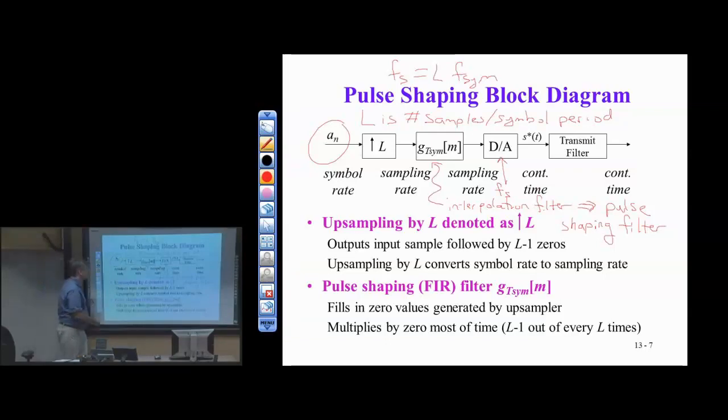Okay, now this is the part of the baseband processing. Then after the D-to-A converter, it will go through some subsequent processing before final transmission. So a modem consists of a baseband subsystem and some analog front end. So this class is focused primarily on the baseband transceiver. We don't do very much on analog integrated circuit design. That's another set of classes for the analog front end of the modem.